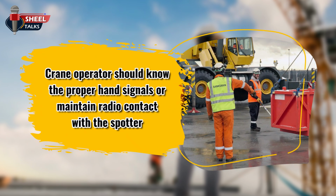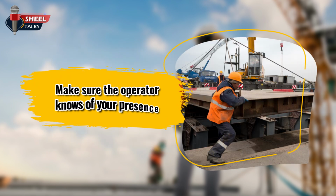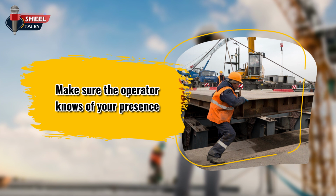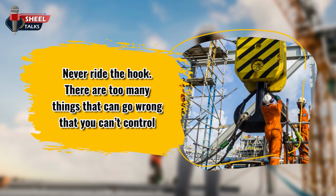The crane operator should know the proper hand signals or maintain radio contact with the spotter. Never walk within the swing radius of the crane unless it is absolutely necessary. Make sure the operator knows of your presence. Never ride the hook. There are too many things that can go wrong that you can't control.